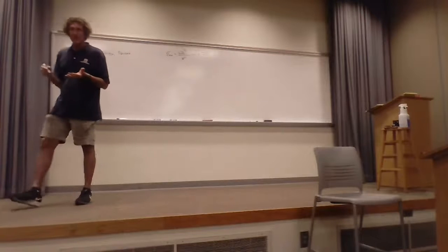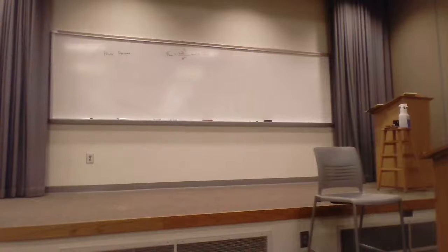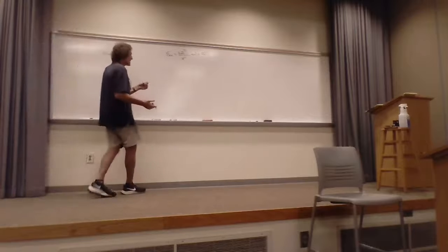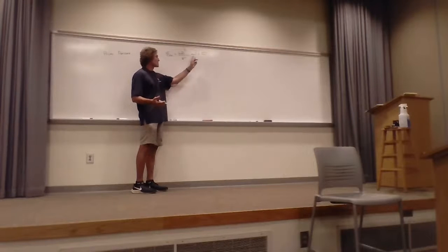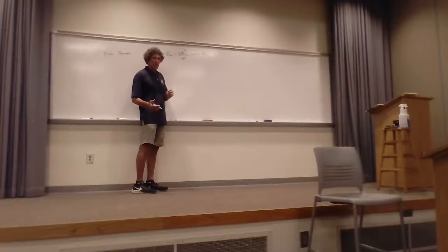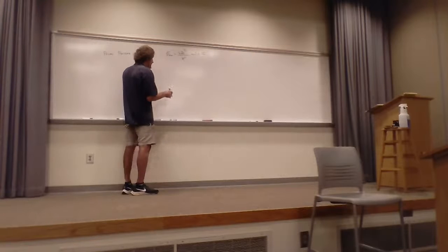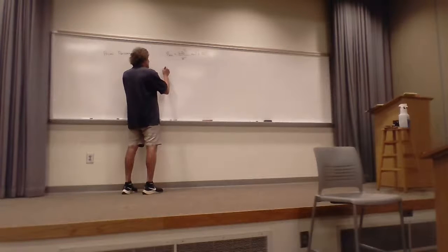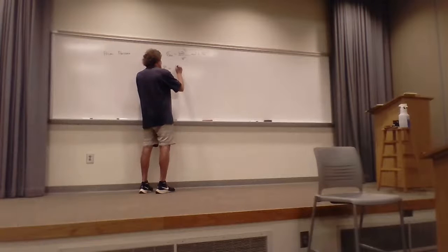Do you all remember that? Now what they always do when they take a look at a power pattern, normally at least, is normalize it to its maximum possible. This is the average power density versus angle, all angles, given R. So when they talk about the power pattern that they're going to plot, they simply say we're going to plot this quantity, and I'll just call it Pn, P normalized. And that's the magnitude of the average power density.